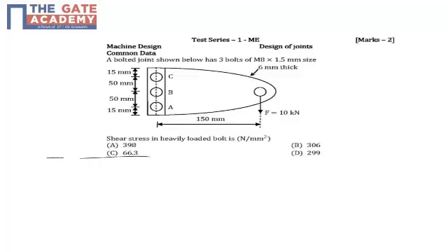Let's discuss a question on machine design, which is a continuation of the common data question. In this question, what is asked is the shear stress in the heavily loaded bolt. Because this is an eccentric load, we split this into three parts.